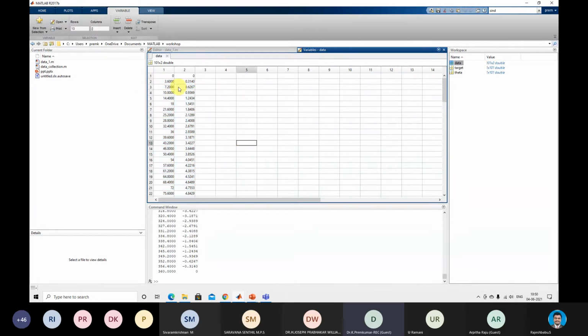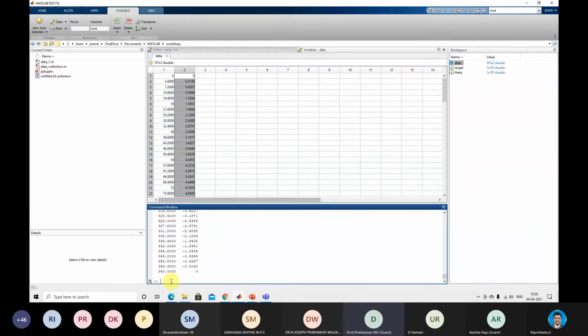So here there are only 2 data. One is input data, another one is target data, okay? So it's going to be considered as a training sample for that ANFIS training. In order to execute that ANFIS training process in Matlab, you just have to type anfisedit, okay? anfisedit.